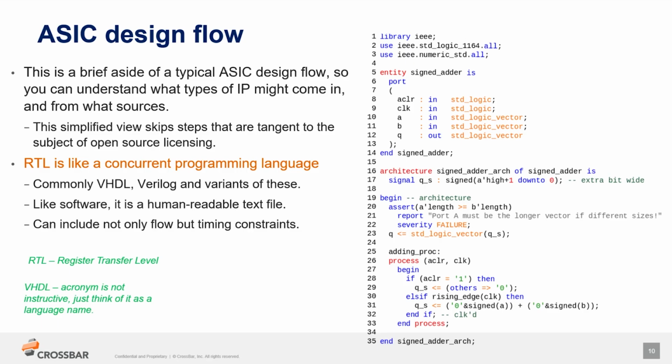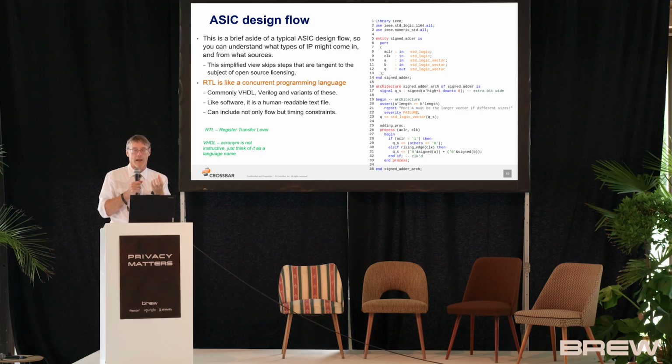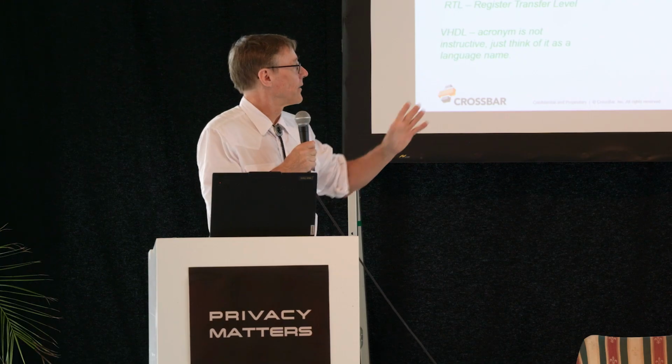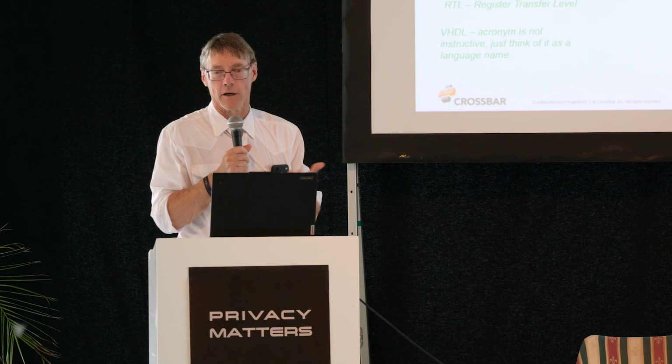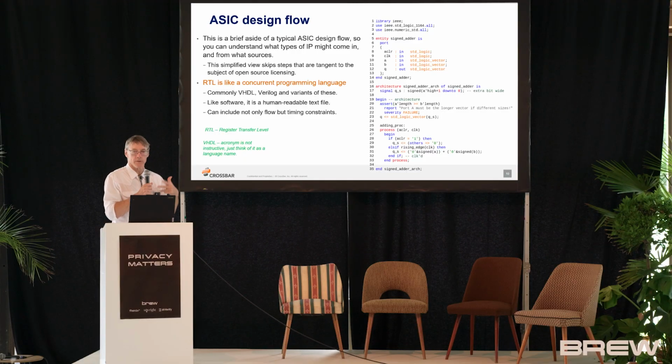Chips are generally designed, the bulk of the logic is designed, in what is essentially just a concurrent programming language. It's a copy on the right of some source code. It looks like software, but the only difference is it's describing concurrent operations. So that can be open source, right? It's a text file.